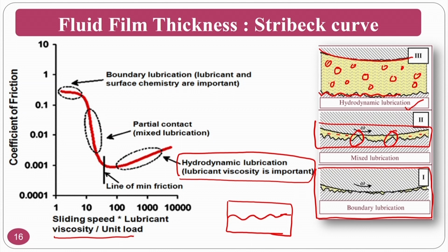This hydrodynamic lubrication zone is what you use in elastic emission machining, because of the rotational effect of your tool as well as the normal load, the abrasive particles are guided and at the same time chemically react with the workpiece, forming a layer, and the material removal takes place.